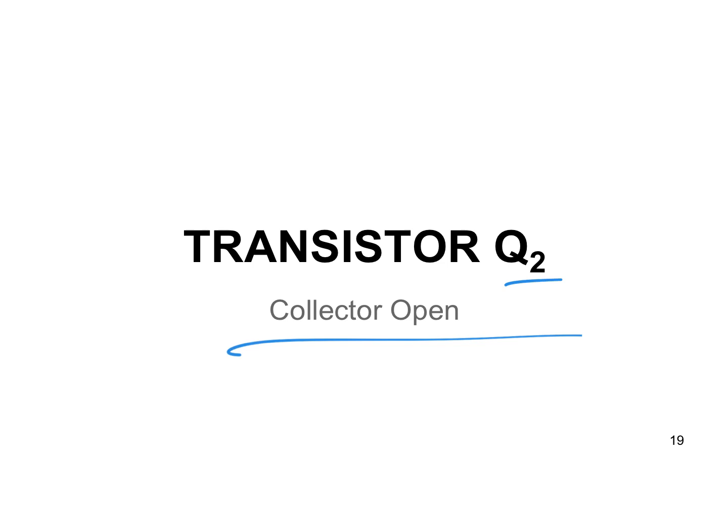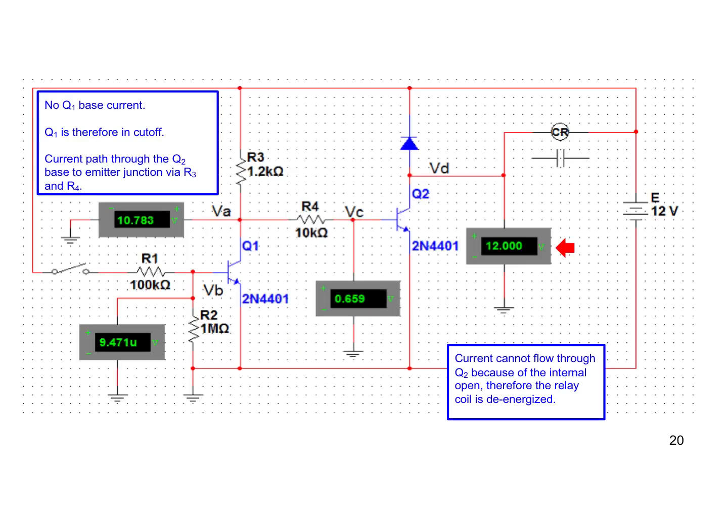Q2, collector open. This one is the Q2 collector. And there's no magic to this. It's just basics. You have to know how it's supposed to work before you can troubleshoot it. Sometimes for real circuits, you need to isolate, unsolder, and connect things to sort out the fault.